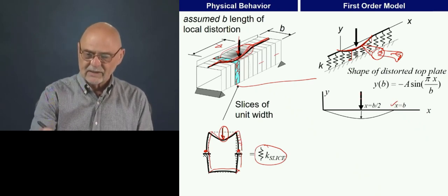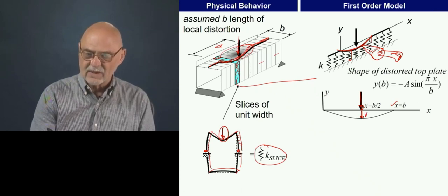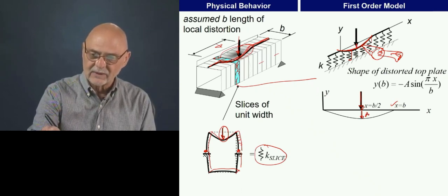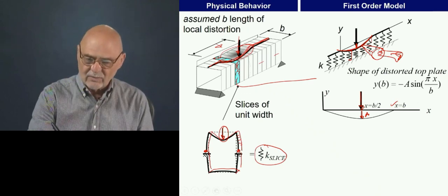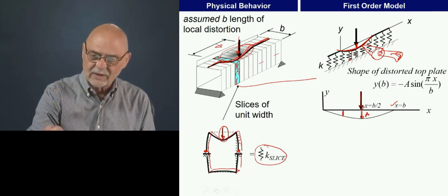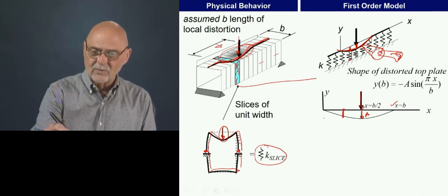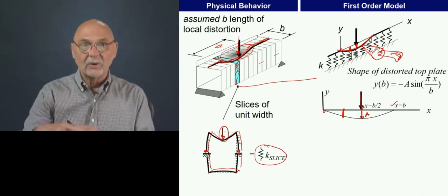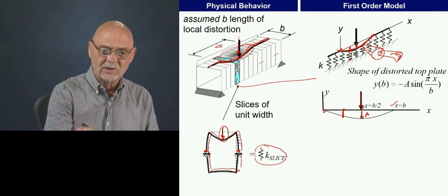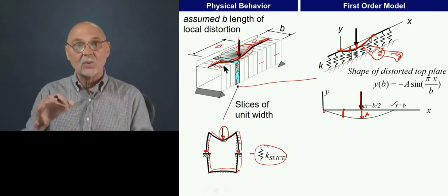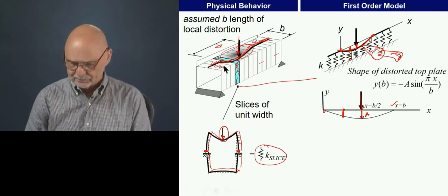So we're applying the load here, and we get a certain amount of deformation right there. But if we move a little bit away, for example right here, we'll get a little bit less deformation until finally we move so far away that we're out of the affected zone. We're kind of in this region here where it doesn't even know we're applying a point force.